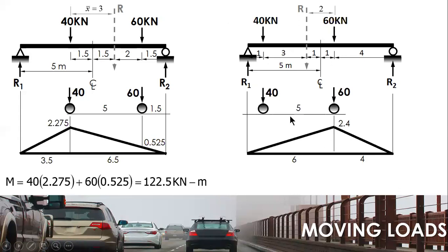Then you place the loads, 60 and 40, with a distance of 5. To get the ordinate under 40, we use the slope again: 2.4 divided by 6, slope times x gives y, 0.4. Then the moment there is magnitude times ordinate, 160. This is the same value we got using the deformable bodies solution.